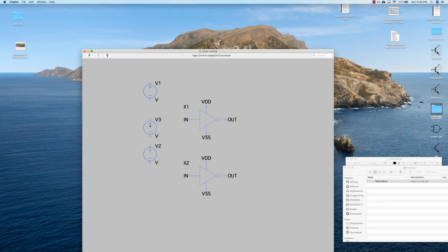And then something for the inputs. I might end up needing to just copy those, but anyway. Okay, so let's say the VDD, I'm just going to have a 1.8 volt and no DC series resistance. Let me just move these guys here. Give ourselves a little bit of room.